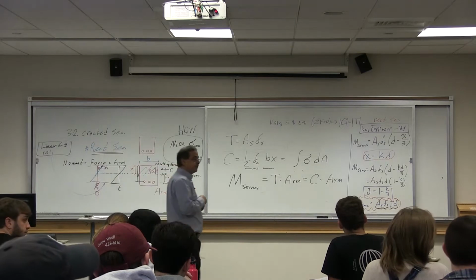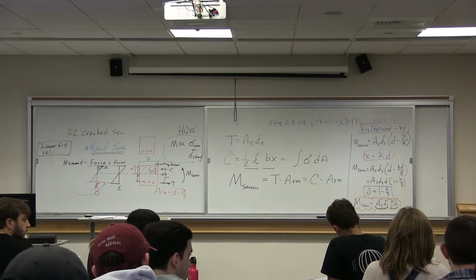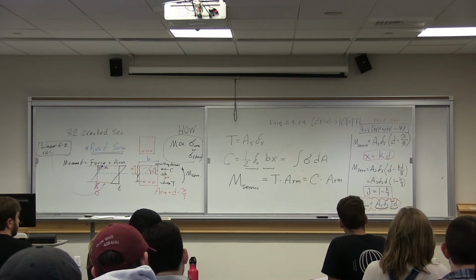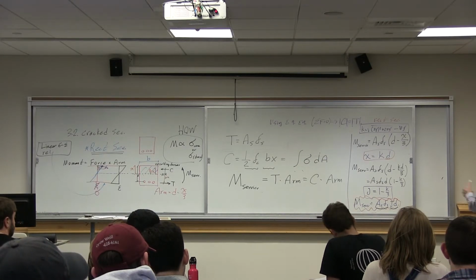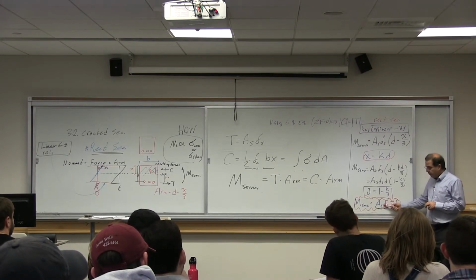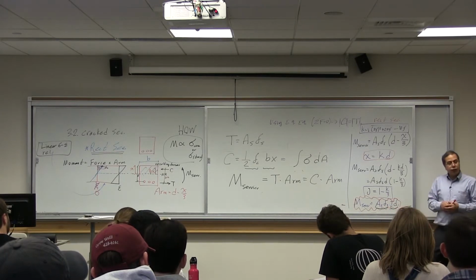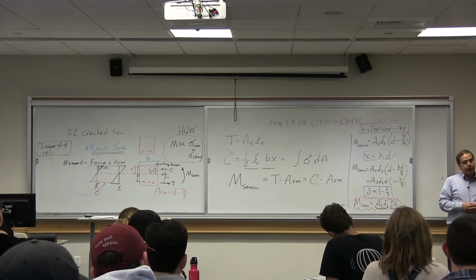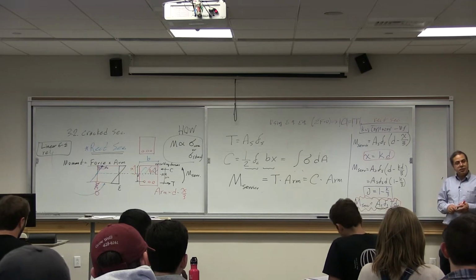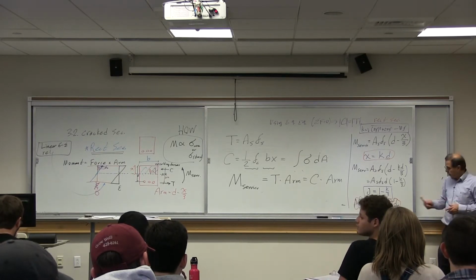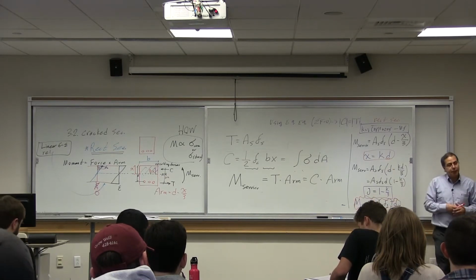Professor? Yes. So when we're talking about under service conditions, when will we use 1/2 of the forces still? So that goes to, we'll look at an example in a moment. This Fs could be any number that you want. You can say Fs, I want to be 1/2 of Fy. This is the stress in the rebar. You can say I want to limit the stress in rebar to 1/2 of Fy. So if this is 1/2 of Fy, from this you can find how much moment you have. We'll look at an example in a moment.